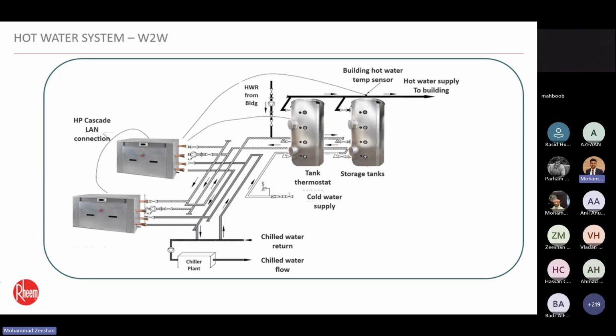What it does is the refrigerant on the primary side exchanges the temperature from 14 degrees to 7 degrees. So it basically gives out that delta T of 7 degrees to the refrigerant, and the refrigerant then works in the vapor refrigeration cycle and gives out the heat, where you have on the secondary side piping similar to our air-to-water heat pumps, where you have water on the other side as well, which exchanges the heat with the tank. So a similar setup as the air-to-water heat pump, except for the fact that there is an additional piping on the primary side coming in from the chilled water.